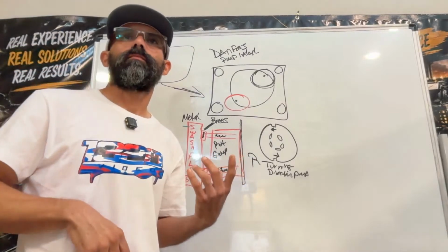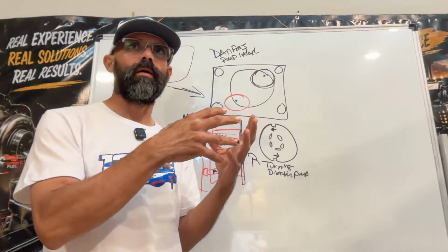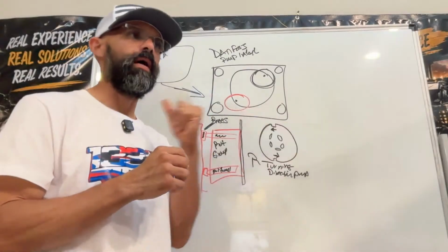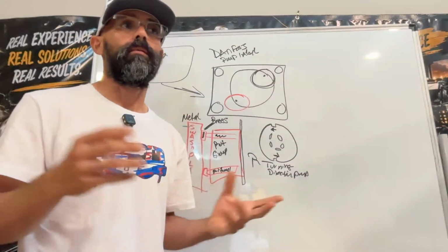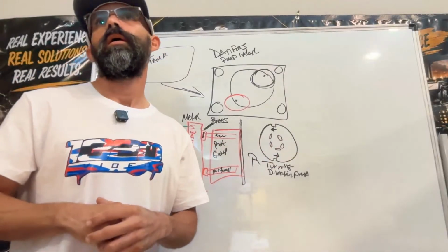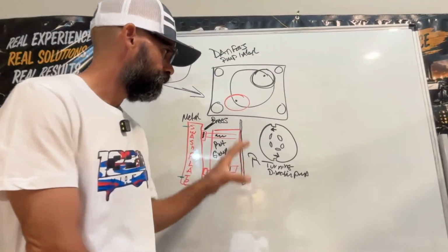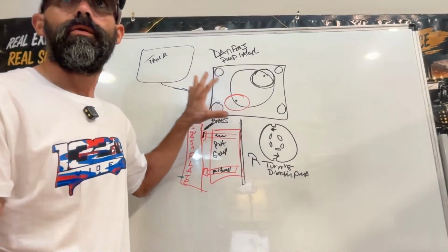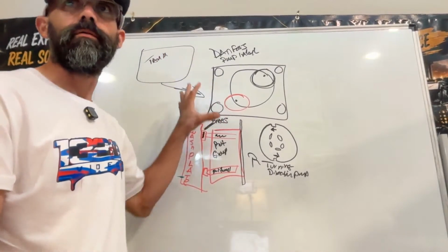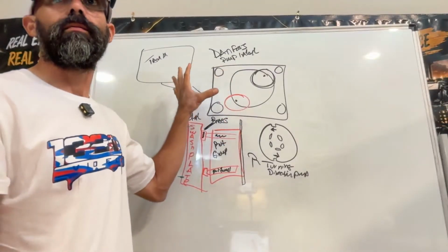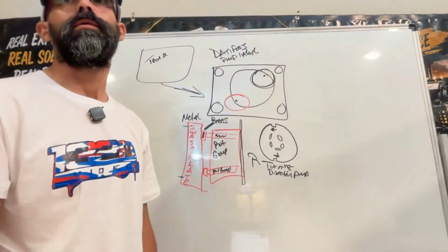So yeah, I make sure that when I send equipment out, it doesn't come back with the same issue. If it came back because one of the boom cylinders is now leaking, okay, let's see what happened. You know what? The cylinder seals were worn out. But you have to make sure you inspect the pump, and make sure what caused the pump to fail. And this is not about doing it quick and, yeah, here you go, here's your equipment back.